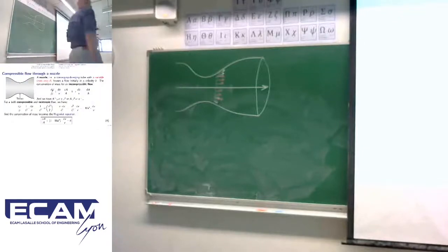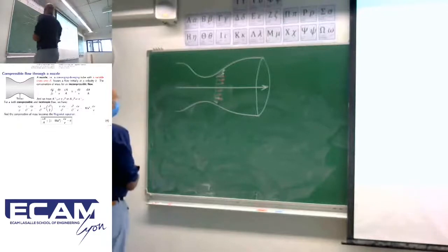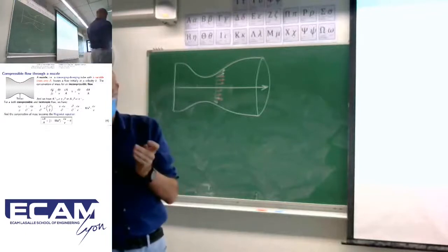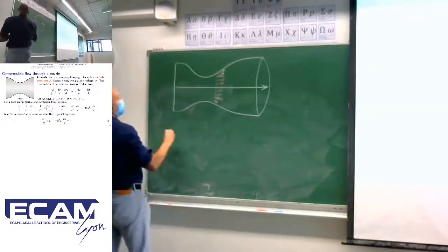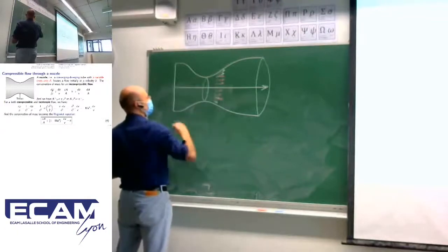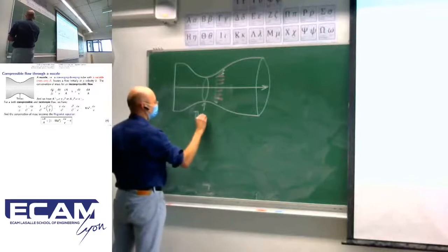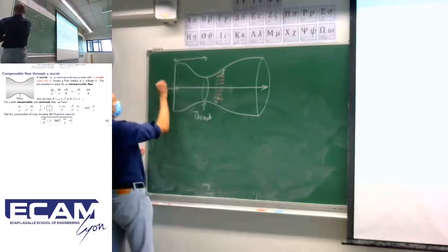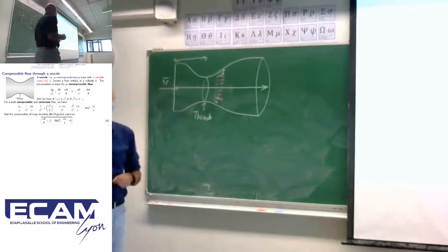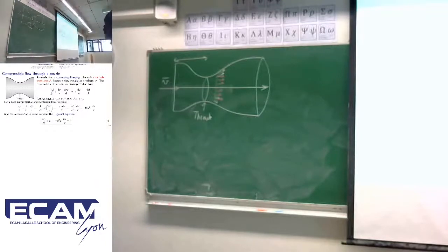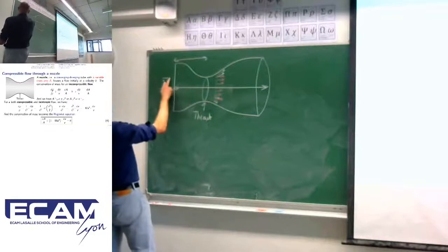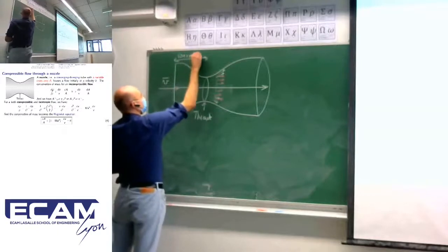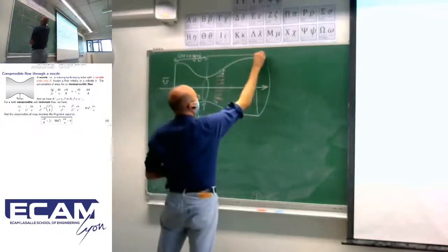So from that, basic definition: what is a nozzle? A nozzle is by definition a converging and diverging fluid tube, with a minimum area, the minimum cross-section, which is called the throat. You have the converging part, with all of the flow obviously in this direction, and we will suppose that the initial speed at the entrance of this nozzle is called V, with the usual bar that means average. This one is the converging part, and once you pass through the throat, you have the diverging part.